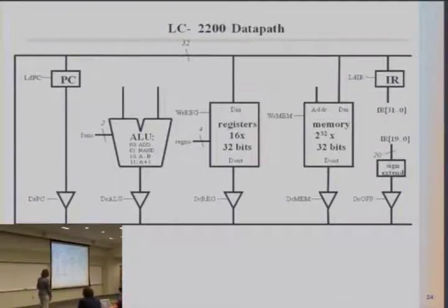So let's see if we want to perform, again, this addition. What do we do? We have a PC that needs to write something into memory. Well, we are adding something called the memory address register. What do you think? Why? Basically, this PC will write its information in MAR. Why don't we just let it load into memory? Because whatever comes in will leak out, and it won't really be available in the next cycle. So we basically store in the memory address register whatever PC gives us as the address.